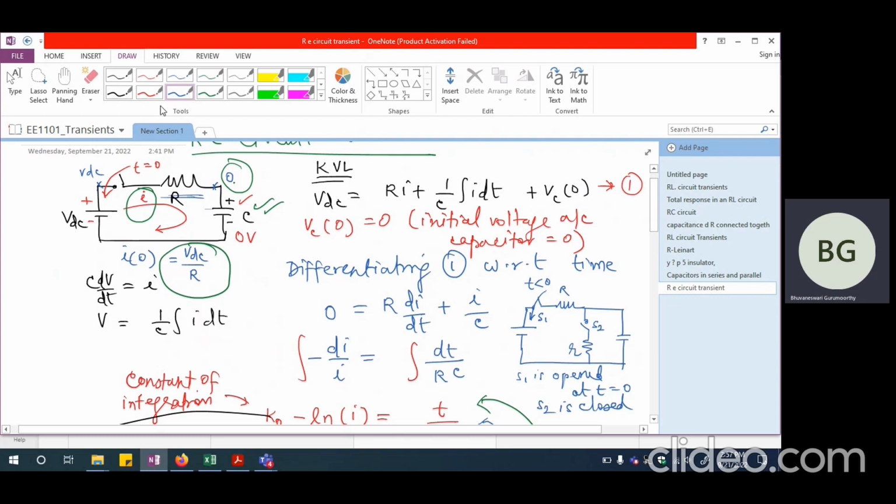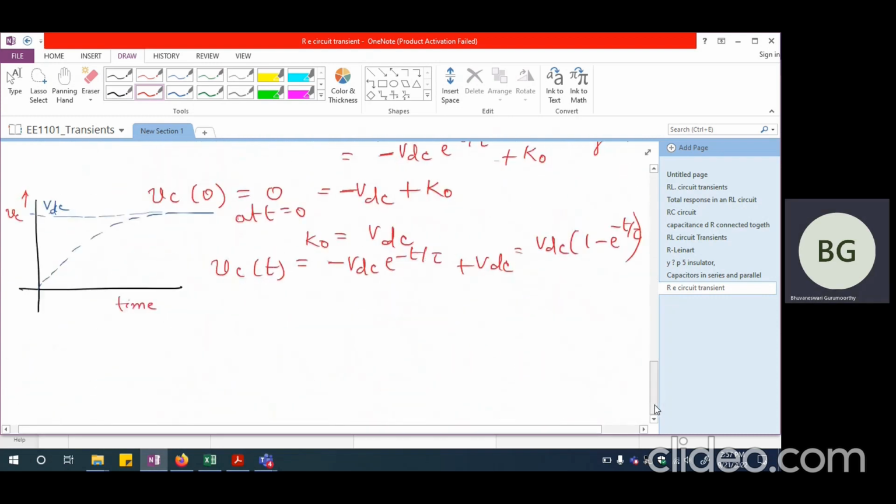So now I'm going to have the capacitance having plus here and minus here. The moment this resistance is connected, this capacitance is not going to keep quiet. It will try to discharge a current in this particular direction. So this is going to be I dash. If I try to derive an expression for I dash, let me try to draw the circuit once again. This is R and this is going to be the capacitance, and this is plus, and you're closing this switch. This is small r. So I'm going to have a current like this, which is I dash.